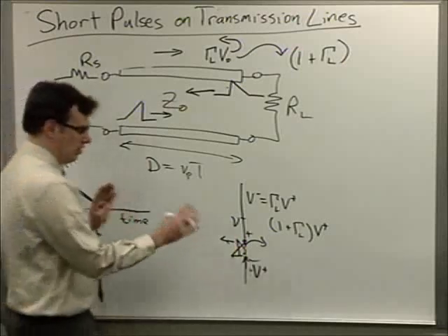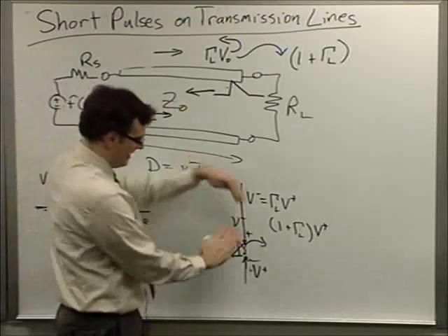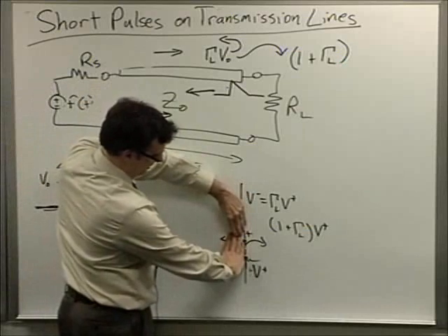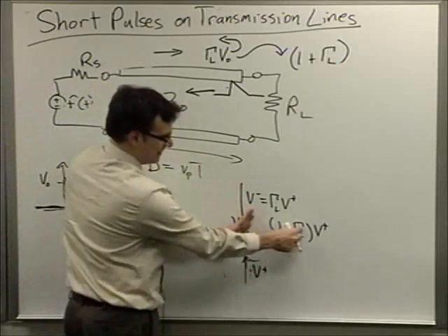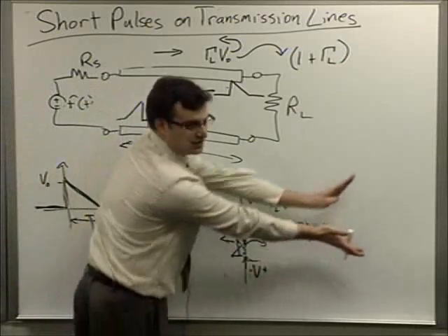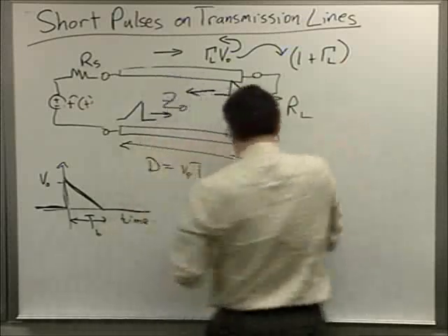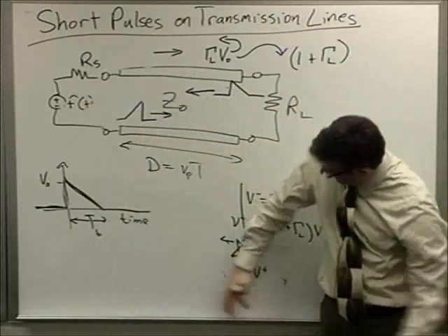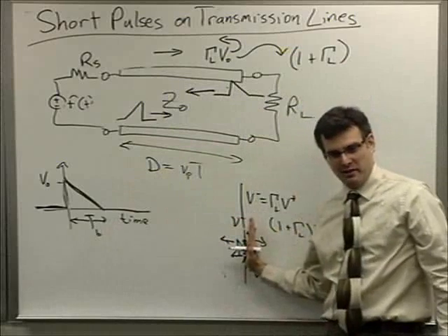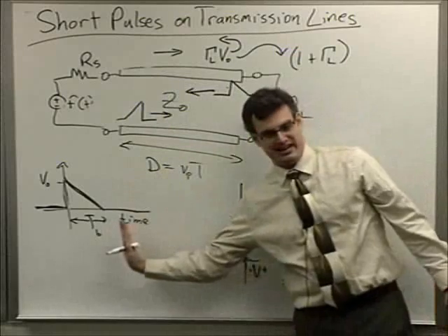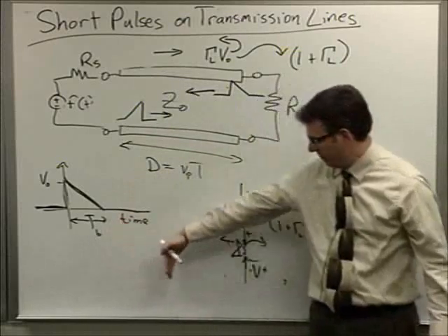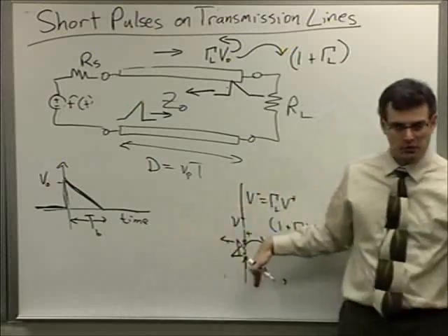And so the way it works out is that if you were to animate it and ignore what's coming out of here, a perfectly formed 1 plus gamma sub L pulse will come out of the line. If you ignore what's going on over here, a perfect gamma sub L pulse will emerge out of that junction, and a perfect pulse will be absorbed by that junction.